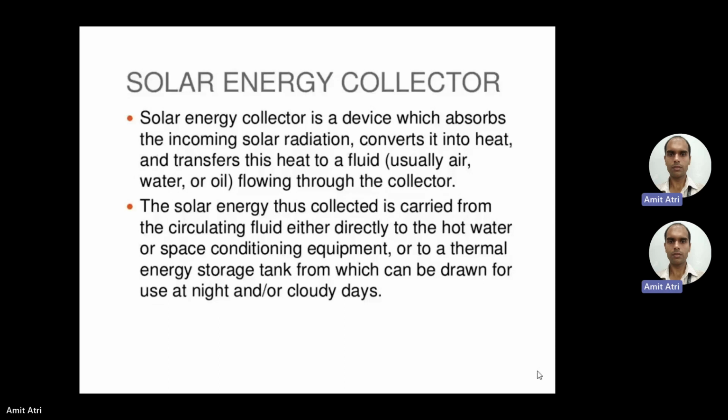Solar collectors are classified as low, medium or high temperature collectors. The name indicates low temperature, medium temperature and high temperature. Low temperature collectors are used for smaller non-intensive requirements common in the household, usually less than 150 degrees Celsius. Medium temperature collectors are used for heating water or air for industrial and commercial use, in the range of 150 to 400 degrees Celsius.